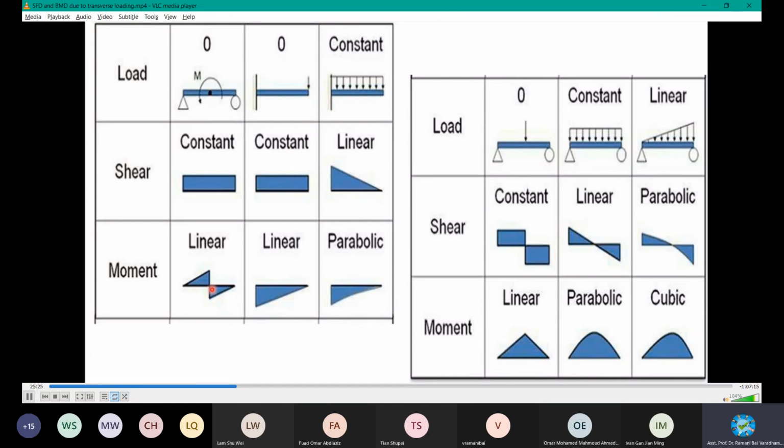This one is constant. Coming to a constant point load, start here: moment, there is a reaction, right? There is a reaction, and another thing, the reaction is not causing the moment here, because it's a fixed end. Note this point, underline this word. Because it's a fixed end, there will be a fixed end moment. So either you derive or you have to remember those formulas to apply. Whenever there is a fixed end, it will impart a reactive moment.